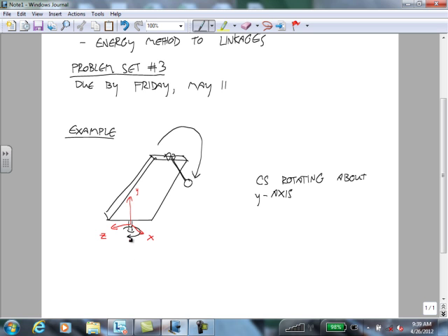You could do it either way, but to me, this is the simplest way. Either way, the rotation of the plate needs to be about a vertical line. So if you have the coordinate system oriented, then your omega vector is going to have an x and a y component. But this way, if this is your body 1, this is your body 2, then omega 1 is just equal to 0, negative 100, 0.